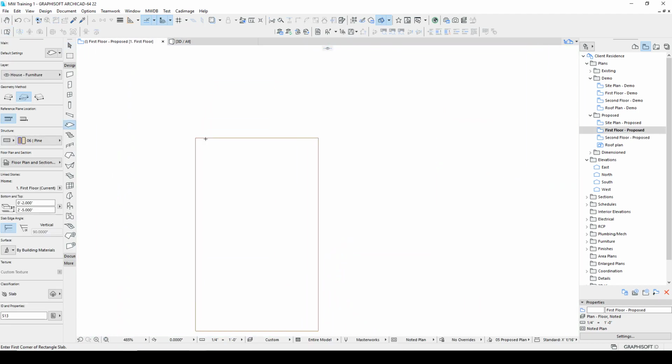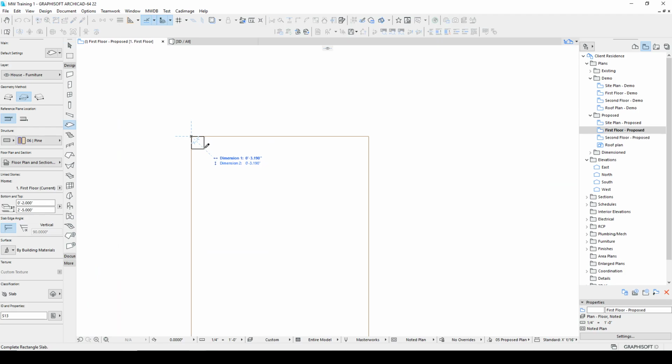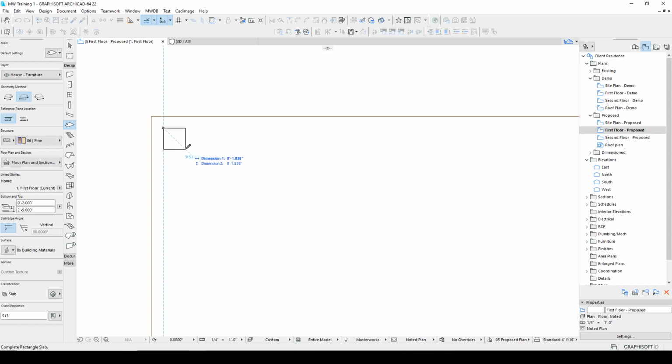And then I copied the properties. I'll put my cursor there, and I'm going to go X 1 inch, Y minus 1 inch. That starts my box here, and I want a 1 3/4 leg by 1 3/4 leg. And then I'm going to make the top of it go from 29 minus 2 inches.